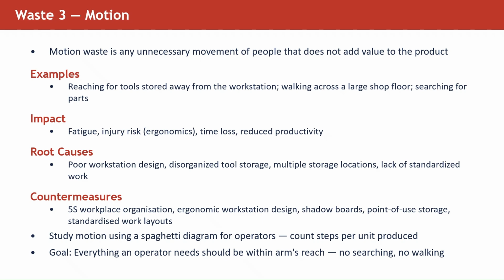Usually the root causes for this are poorly designed workstations. So workstations need to be organized keeping ergonomics in mind. Ergonomics is a very important part when we are designing a workstation. When we organize the tool storage, where a person can reach, put it on a standard work layout,